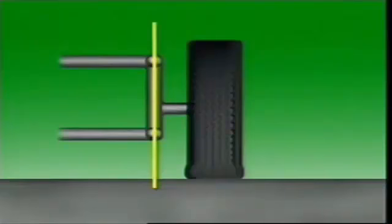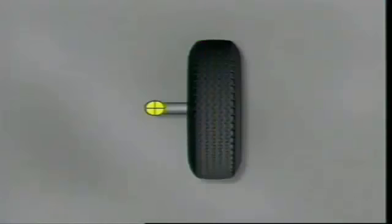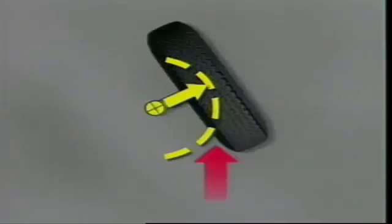With a vertical steering axis, no self-centering would occur. The wheel would pivot on a radius with the steering axis as its center. This would introduce a turning moment on the wheel. Road shocks would be transmitted back to the steering wheel, and steering would be difficult to control.